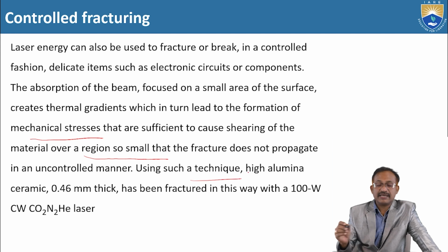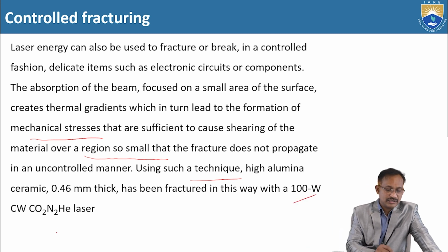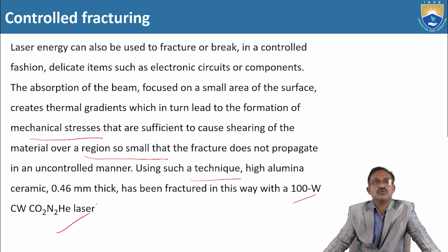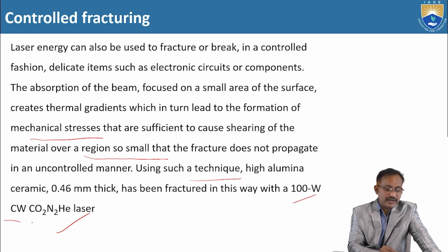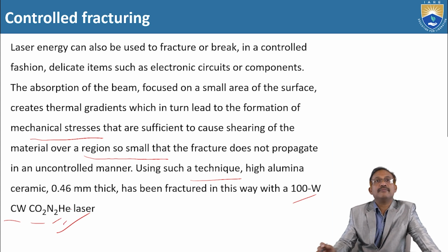Using such a technique, high alumina ceramic 0.46 millimeters thick has been fractured in this way with a 100 watt CW CO2-N2-He laser.